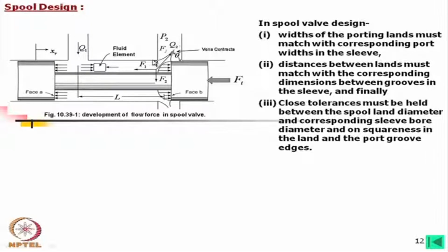So, to avoid that, a small breaking of such edge is done, that means you may find, if it is measured, a small, not chamfer, you can say a round-up is done at these corners. Okay. However, it is better to keep these edges as sharp as possible.